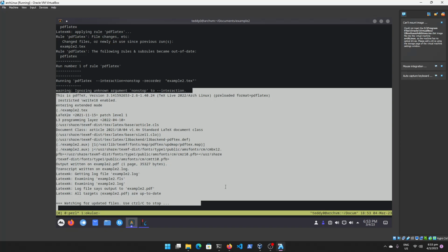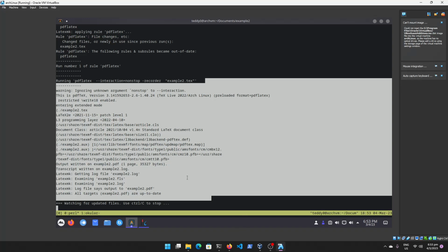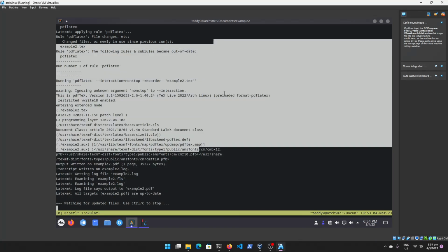You can do something similar with OpenFOAM as well, I believe. Honestly, I have not tried it myself yet, so I would not know what is the best approach to use 2 computers to work with OpenFOAM. But you can SSH into a Linux machine to do OpenFOAM, and then maybe use a Samba folder to port over those files you need to visualize in ParaView on the Windows PC. A lot of possibilities you can do. There are lots of things you can do with this sort of workflow, as long as you are SSHing into another laptop or at home.